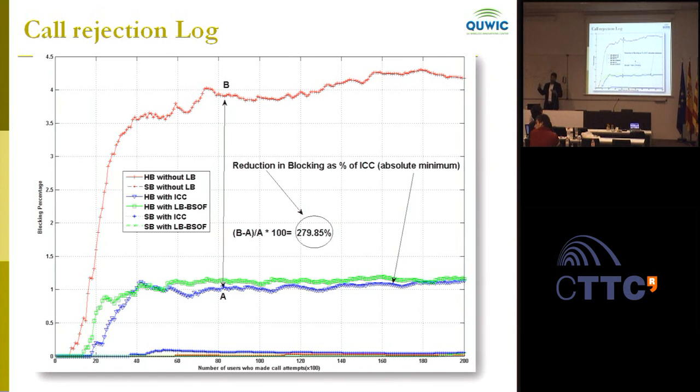Getting my point? Have you done some dynamic system level simulation on call blocking? So you understand, you model traffic with two parameters: arrival rate and call holding length. Your arrival rate is Poisson, and holding length is exponentially distributed. These two parameters you set to get a typical amount of Erlang traffic. Since it's a random variable, a random number of users are arriving and holding the channel for a random length of time, but still they have an average, it's an IID process. So in the long run, you're going to get a stable blocking, but not a straight line. So is averaging going on? Yeah, it's a kind of running average.